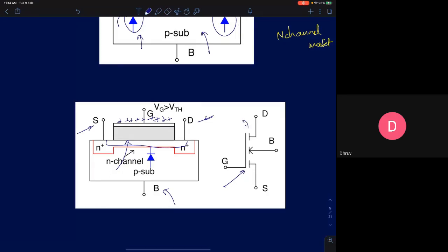The dashed lines show that when the gate voltage is 0, there is no channel between the drain and source. As you increase the gate voltage, a channel is formed. So that's why these dashed lines indicate that. An enhancement mode MOSFET is represented by 3 dashes here, and then the 4th terminal, bulk, is shown as an arrow pointing inward.